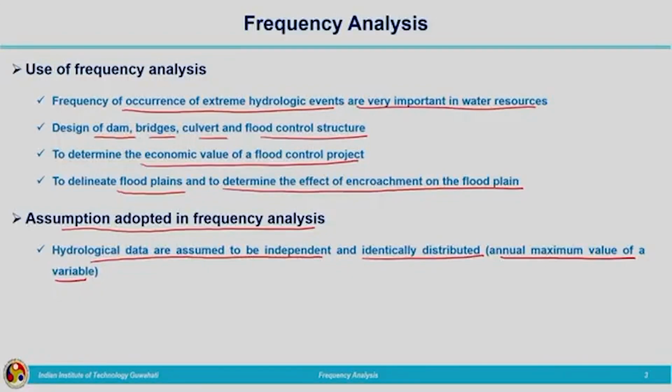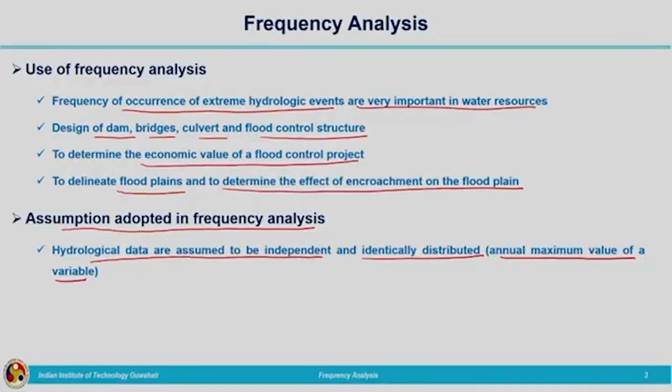That assumption is valid because this year's annual maximum rainfall is not dependent on the next or the previous year's annual maximum rainfall. For the entire data set, we will be considering a single distribution.